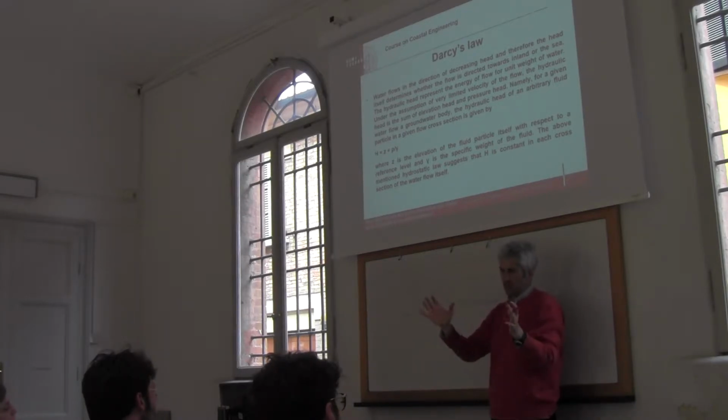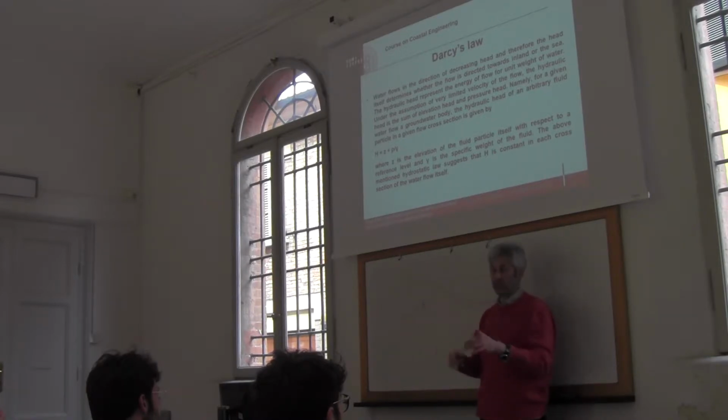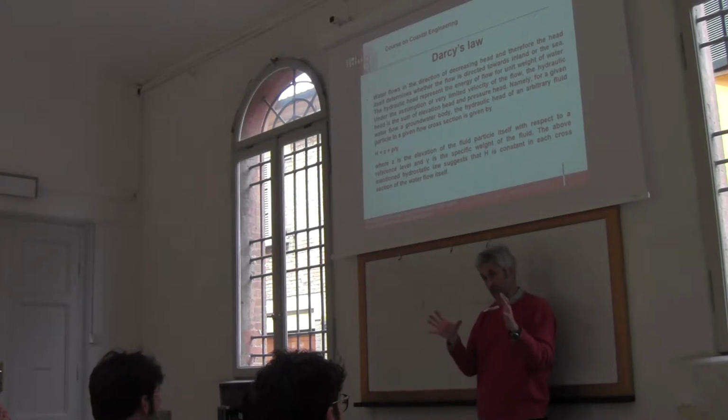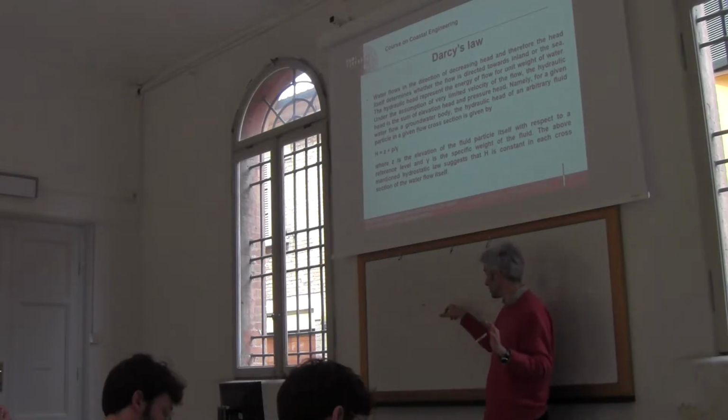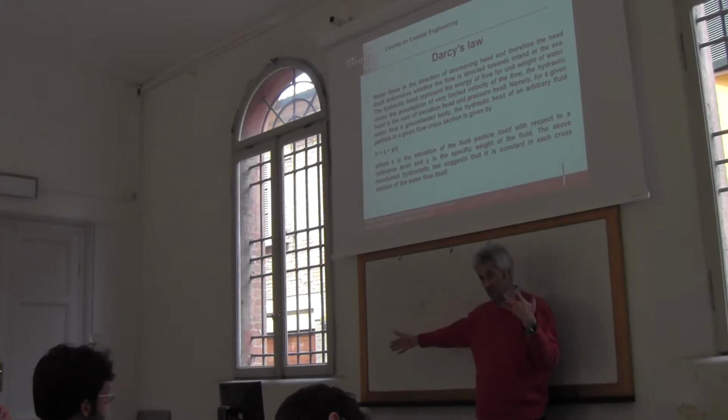You may say now, why is that? Because this water is traveling through a medium to get to the water particle, so some pressure should be spent to travel through the medium. My reply is, keep in mind, the velocity is very low. We are close to static conditions, and therefore you don't have any dissipation of energy traveling through this medium.